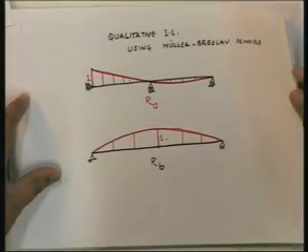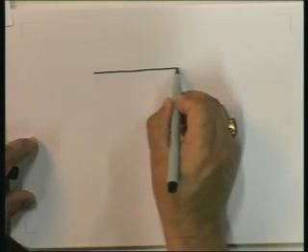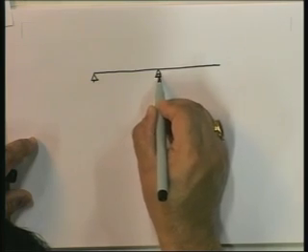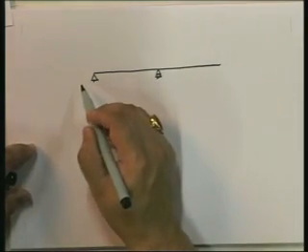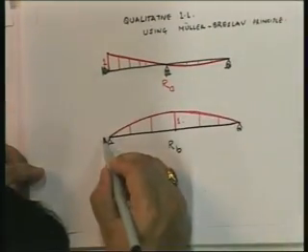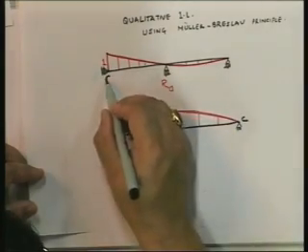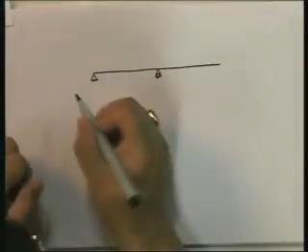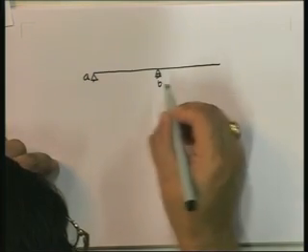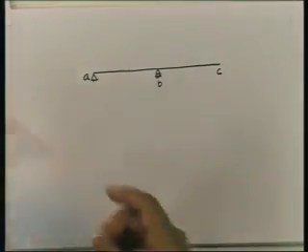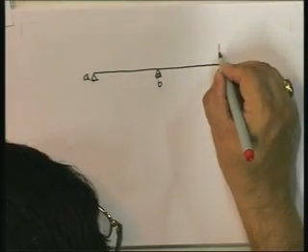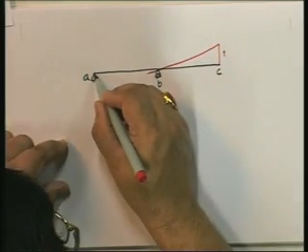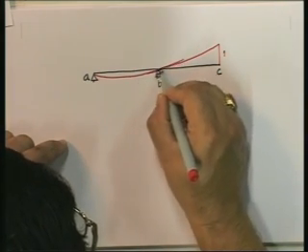Now, let us look at RC and the bending moment. So, remove the restraint at C, this is for RC, give it a unit displacement and find out the deflected shape.